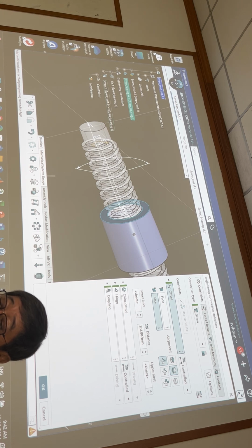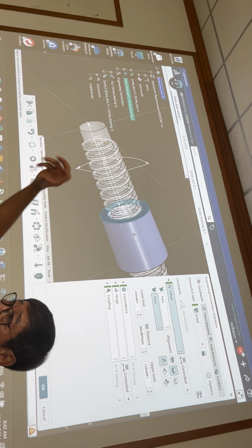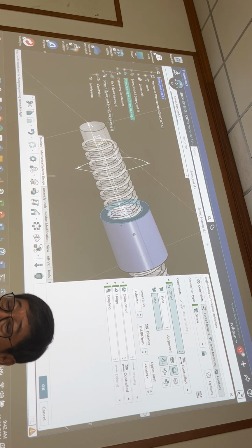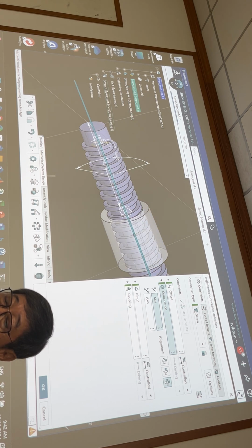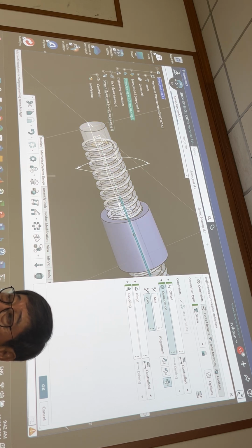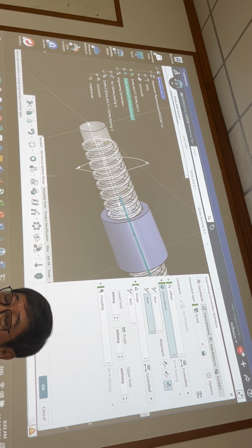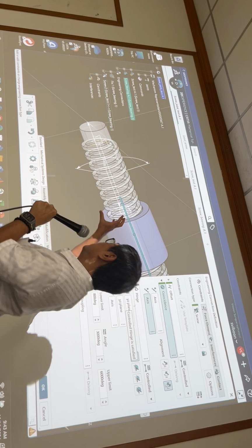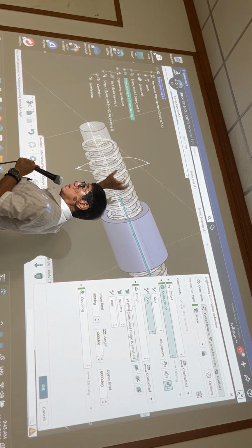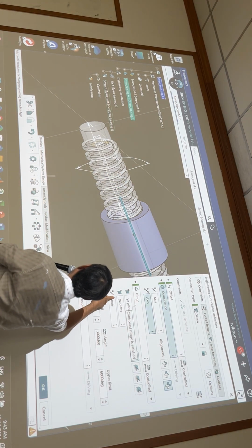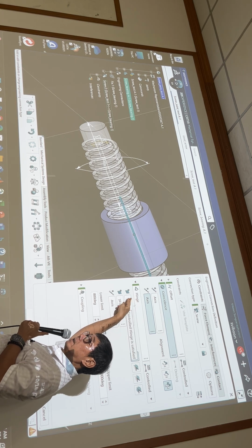The other one is coincident, because it rotates, right, sliding around this one, so coincident between this axis and this axis. The shaft of this and the shaft of this are the same, the axis of rotation, the rotation angle, because it rotates. So you have an angle here, hinge or angle, right?